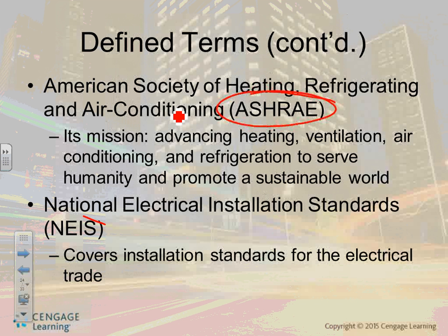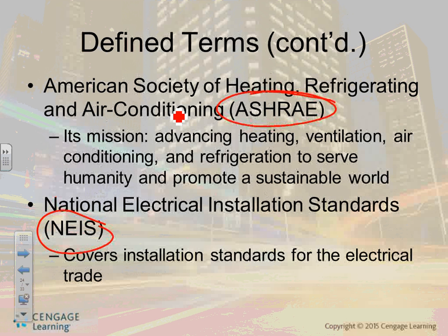And those guys, National Electrical Installation Standards, they'll give you NEIS, for example, installing EMT conduit. I can install EMT conduit in any way, shape, or form. They have a whole book about the best practices. Have you guys used them when you were at Dakota? We have them here in our program. We have a list of, oh my God, a lot of books about rigid metal conduit. How do you thread and bend a rigid metal conduit? The best practices in the industry. So they write books about the actual installation of this equipment.